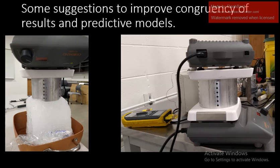If we were to do the experimental test again, we would do something along the lines of the second test, using 2 hot plates. We would need to make sure that the top and bottom surfaces of the cylinder are at constant temperatures, as the hot plates used a duty cycle to turn on and off in order to achieve a certain average temperature. A constant surface temperature on the cylinder would yield more accurate results.